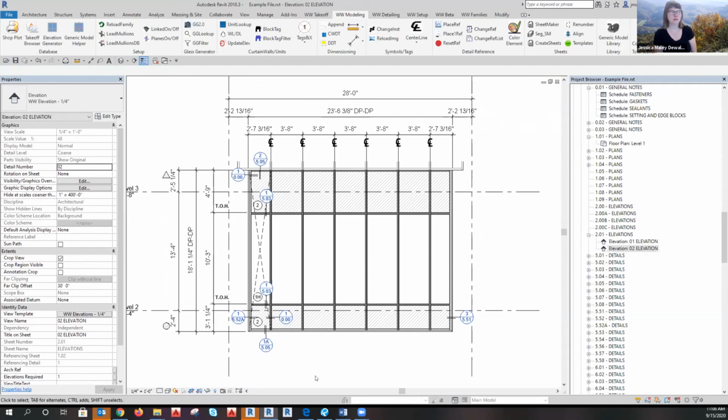What would you enter into the different project field? Is that like different buildings? Yes, that's what it's for. So if you had a campus and you copied the first building to make the second building, but the first building was still in your model, you can mark it off as different project, and the takeoff program won't deal with it. We'll just ignore it.